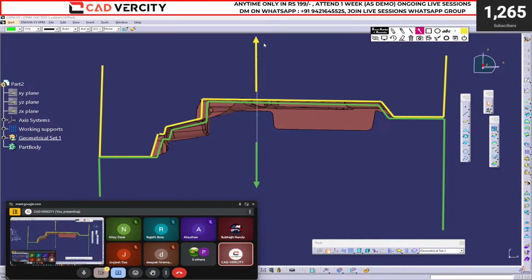So what are ejector pins? Once your part gets solidified, it will stick to your green tool. So there will be some pins which will push your part outside. Once the machine opens the tool, the pins will push a little bit. It will push the solid part, and the part will get collected in a sack. Let's consider there is a sack below the tool.